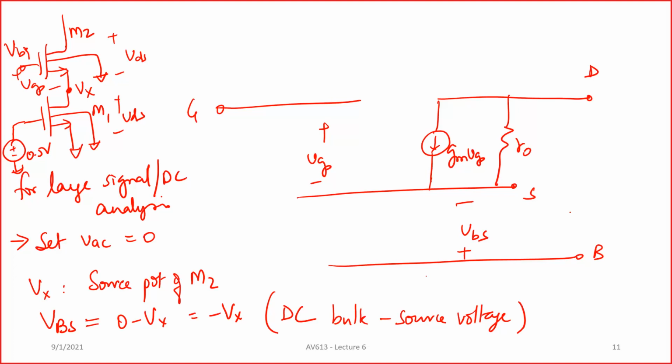Somebody had a question? Yes, sir. Dhruva here. When we are operating at a particular bias point, can we try to define some sort of slew rate for the transistor itself? Slew rate is there. We look at slew rate for op amps and so on. What do you mean by slew rate here? Slew rate in the sense the duration until which the linearity is maintained, because when we do the AC analysis, we can see the drop down at a particular high frequency level, right?